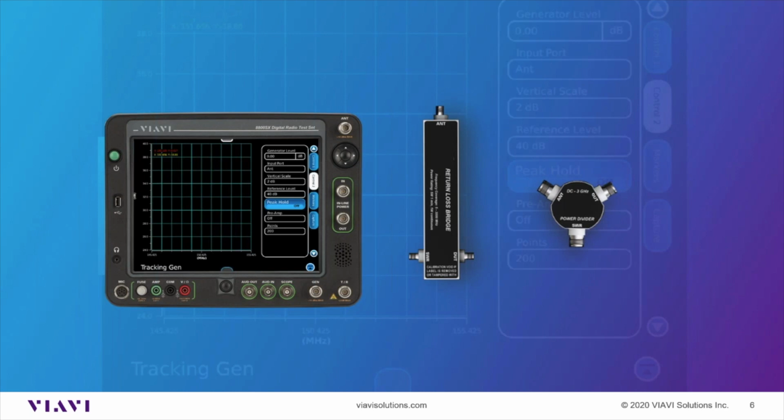And by the way, one of our Daves commented the other day that maybe I ought to tell you how to get to the tracking generator. That wasn't part of what we're doing, but you probably might want to know how to do that. I probably should have told you in the beginning if you're trying to follow along. You'll have the video out here pretty soon so you can follow along. But you would hit your gray tab and you would go to the analyzers and go to tracking generator to pick that up. But that's where it's at. So just with the tracking generator and these two devices here, you can do all of those measurements.